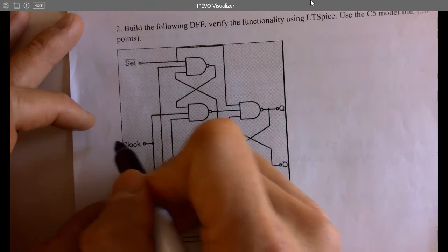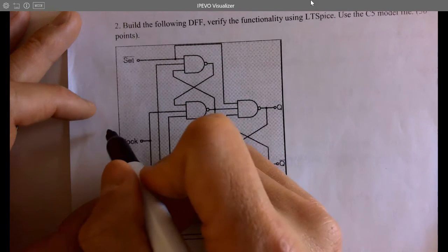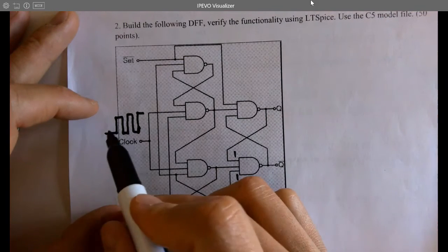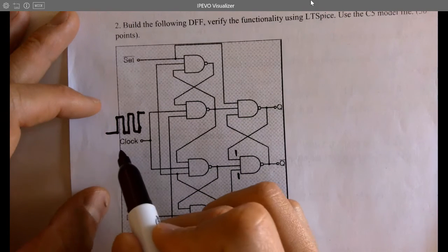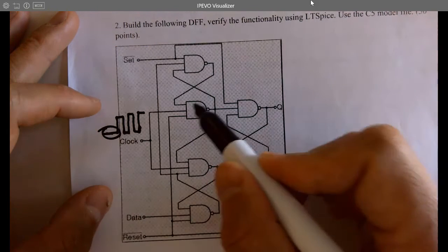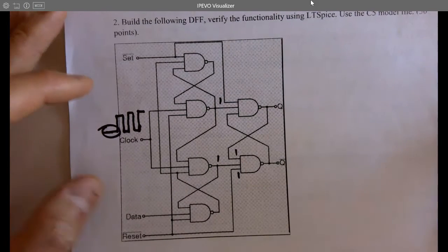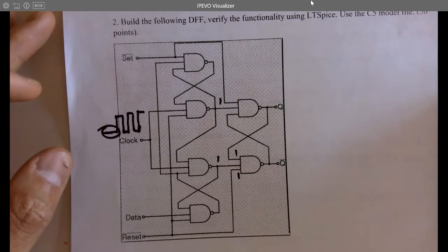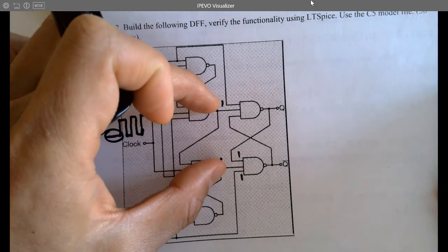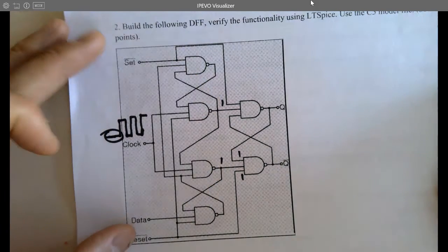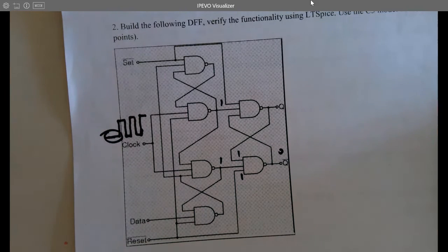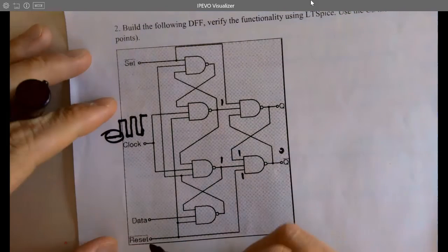Let's do this. So clock, because it's being clocked, before the rising edge, or when we are looking at it after it's powered up, it's going to start oscillating. During the 0 phase, it's going to kill these two NAND gates and give them 1, 1 here. That's working as the initial state. Whenever you got a 0 for the clock, it's going to kill these two NAND gates and give them two 1s. That's the initial state. So you got 1, 1, 1, you got a 0, right? So what about reset?